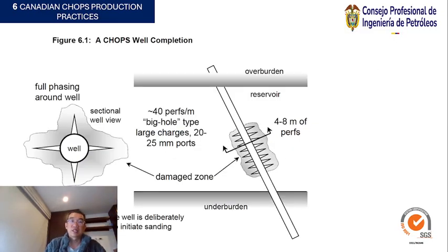This figure is a CHOPS well completion. The zone around the well is deliberately damaged to help initial sanding.